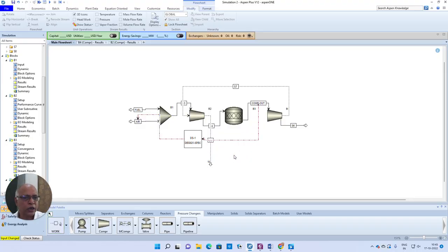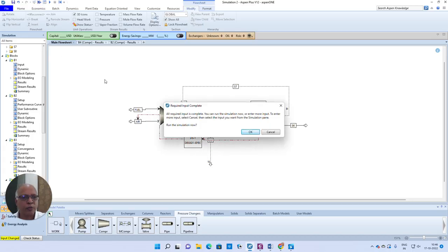that is produced by the process. In fact, we were already able to calculate this, but the advantage of using heat and work streams is that energy delivered from one unit can be utilized in another unit by using either heat or work streams. So this will help you to maintain heat integration, work integration and so on. With this modification, let me run the problem.